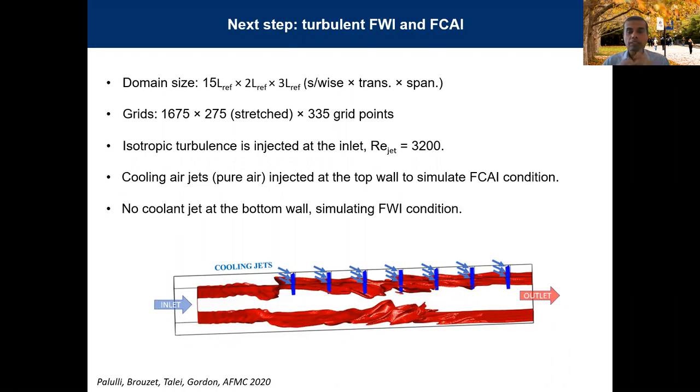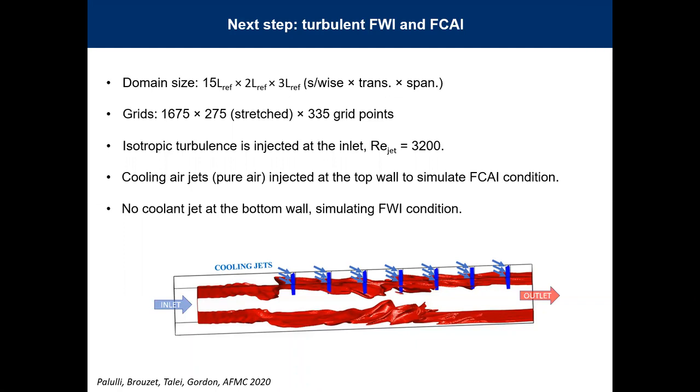Having said that, what you want in a gas turbine combustor is not extinction. What you want is cooling air creating a film of air above your liner to protect it. So you don't want your cooling air to interact with your flame much, but in the final zone of combustion, you want mixing of cooling air with combustion products to lower the temperature. Thanks. No problem.